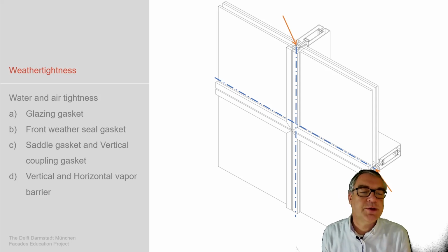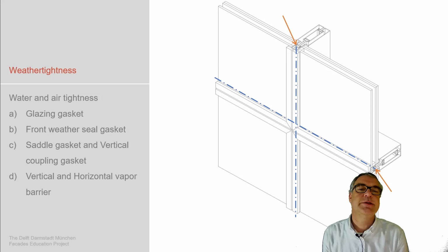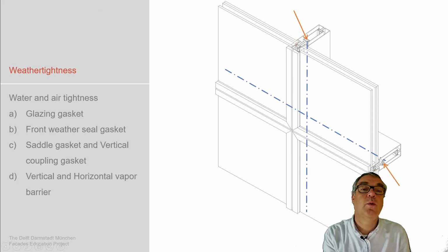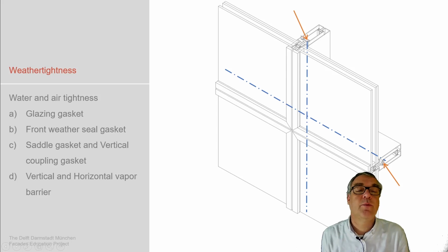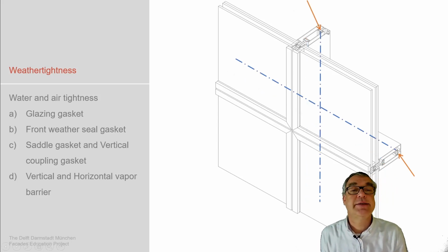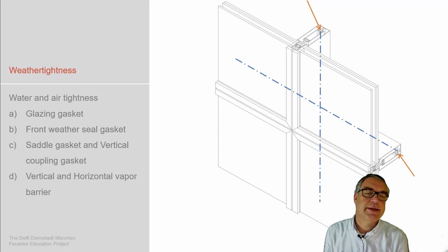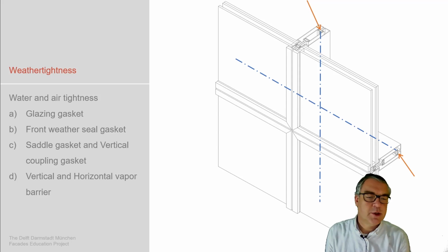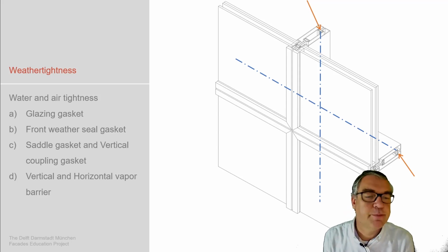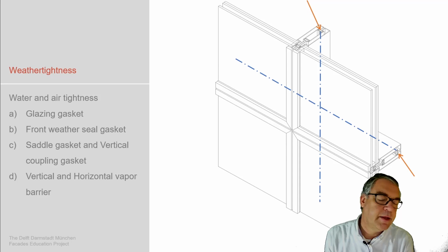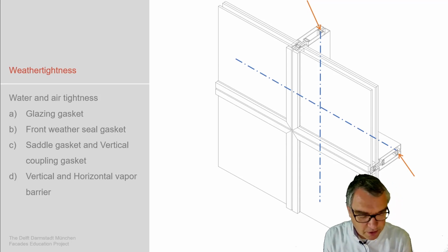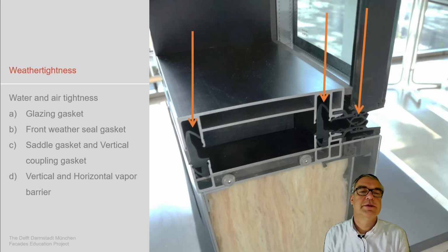Then the outer watertight sealant, which is happening in this position, and then the inner watertight sealant for the outside, which is happening at this position, and also solves the connection in the joint, and then the inner airtight sealant, which has to make sure that there's no humidity coming from the inside into this gasket system. We are using 3 layers, which is the typical setup which we nowadays use for prefab components. If it is an aluminium profile system or if it is a concrete prefab component, these 3 layers are the typical ones being used.